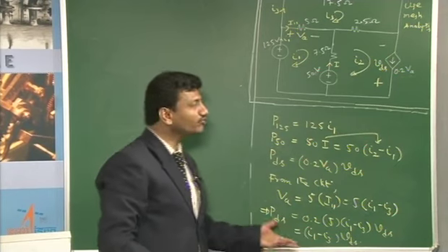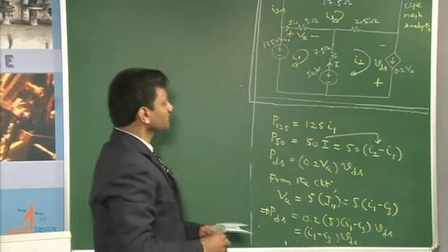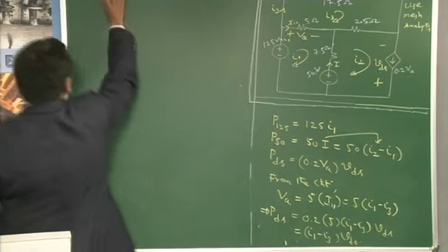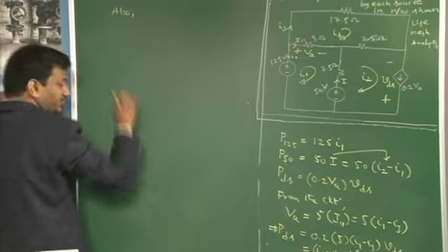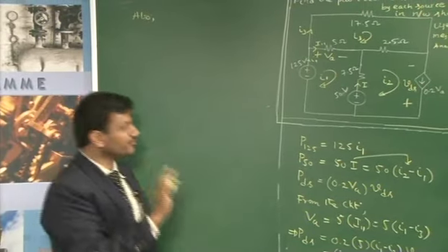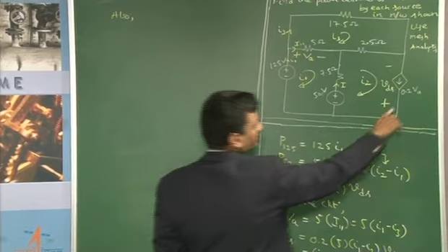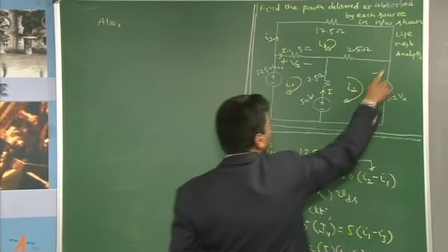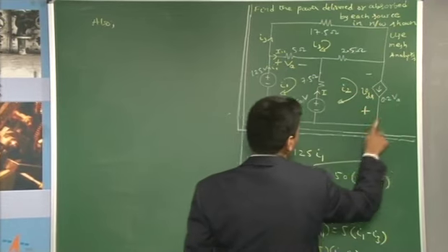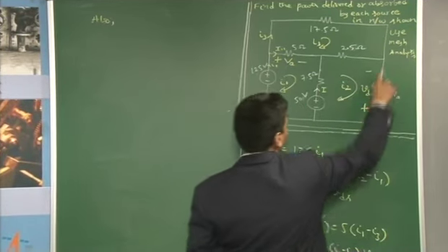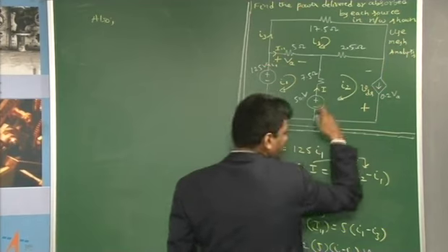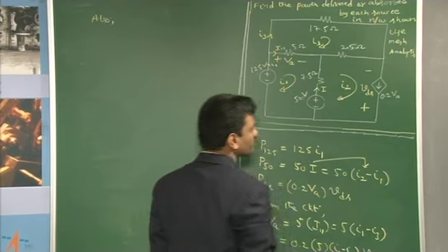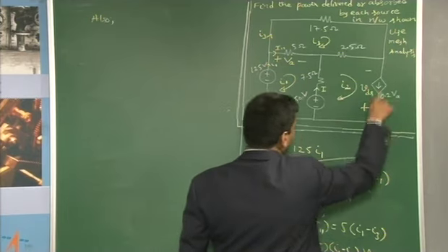So how are they to be found? By using the mesh analysis. Then one more observation from the circuit. Whenever there is a current source in a mesh analysis problem, let us be very careful. Now you find a current source, and this particular arm only belongs to mesh 2, and whatever current flows in this direction should obviously be I2. And in this arm or branch, you are observing the current source to be present, whose value is also what?